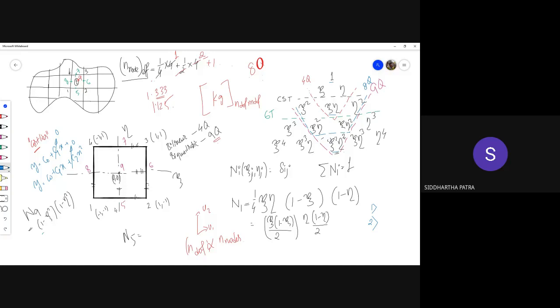So when you are getting a given order of the polynomial, you need to also accommodate all the polynomials which are lower than that. That is a basic rule of getting shape functions. That way the shape functions are complete. So you can always get rid of the highest power but not the lowest power. So this term over here qualifies for both: it is symmetric, and it is also the highest power. That is why you'd get rid of this term.